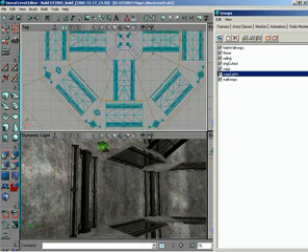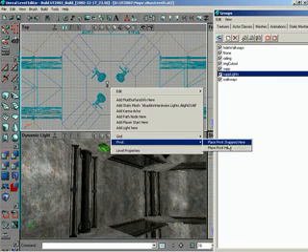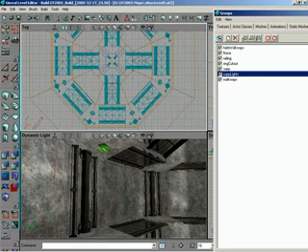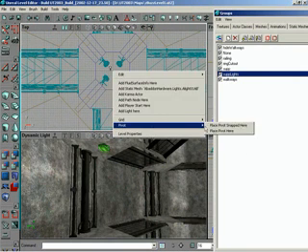And go back to the group, select all in that group, duplicate again, then move them back to center. And while Logan's just duplicating these all the way around, repeating the same process, if you guys haven't noticed by now, that's really what this arena here is all about. It's a really interesting looking map in the end, but it's really mostly about nothing more than a ton of duplications. And by using your groups efficiently, you can make this happen really, really fast.